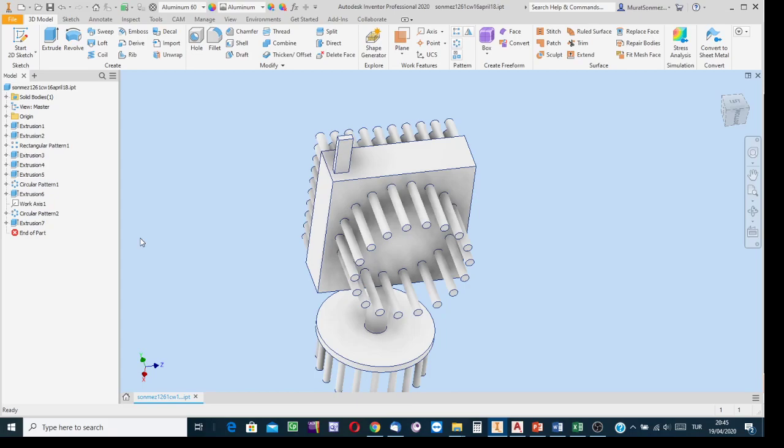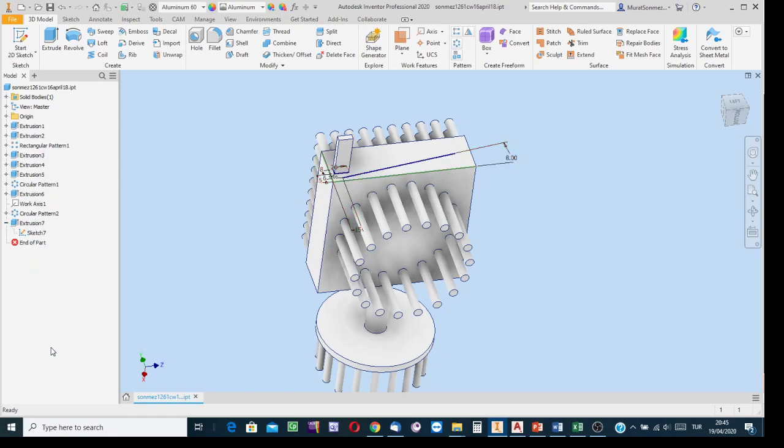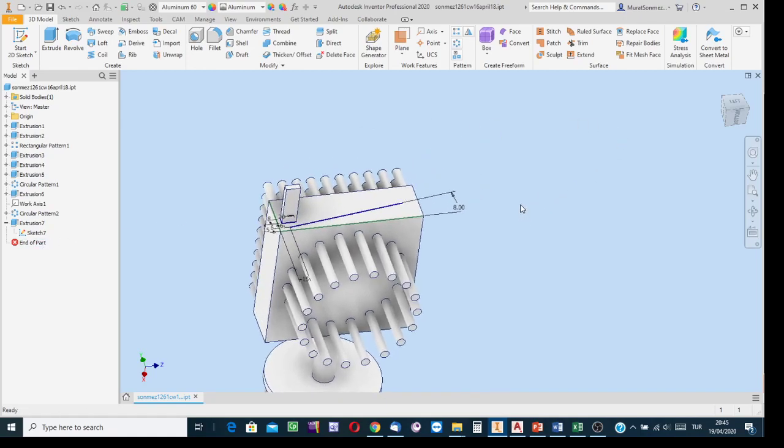It's a path array. Where is the sketch? I need to use the same sketch. This is the icon. Creating that feature, I used the sketch for the first time and it has disappeared. Make it visible: click on the listing arrow and select the sketch icon, right click and visibility. After making the sketch visible, I can use it again one more time. Why? In that case, to indicate this line as the path.